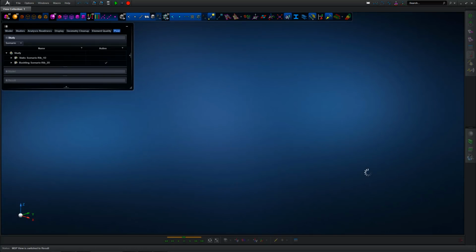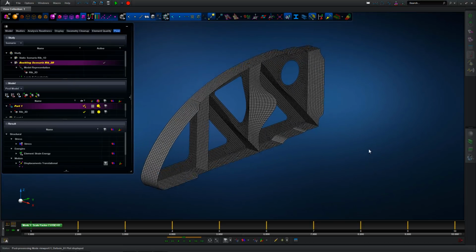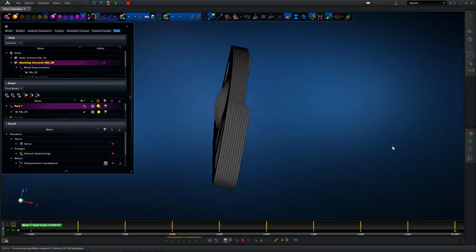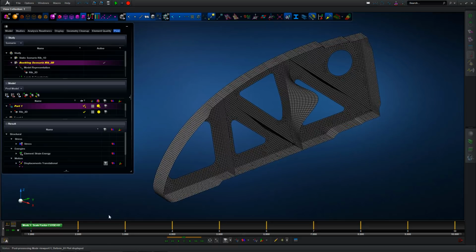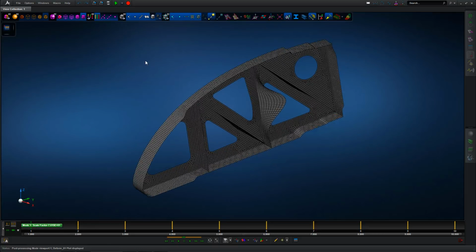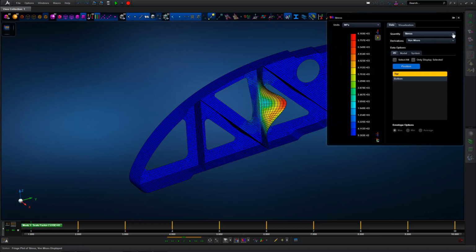to give us our buckling factors, and then we look into the post-processing side of Apex, and we can see we've got our buckling modes with our load factor. A significant load factor is required to buckle, but we can see the out of plane pressure load would buckle one of these shell ribs at the buckling factor 7 as shown on screen.